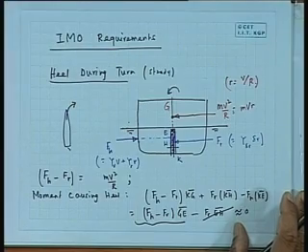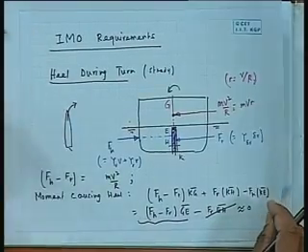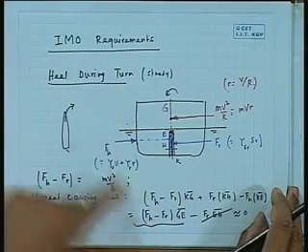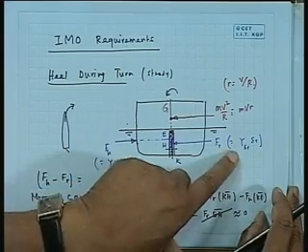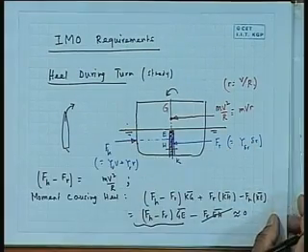So once we know the moment causing this heel, obviously we can find out the amount of heel. So this should be understood. This becomes the moment causing heel, FH minus FR, and you can actually find out what is FH minus FR. As I said, FH is Y_v V plus Y_r R and FR is Y_delta delta_R. So if you know the hydrodynamic derivatives, we can find out.